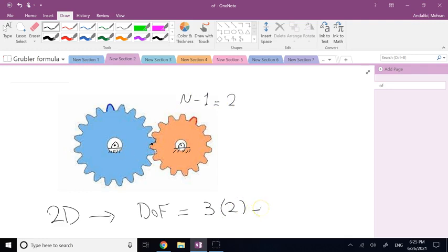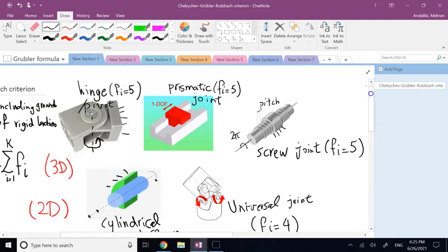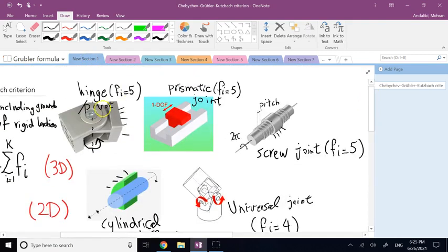Now minus, so here you have 1 pivot and 1 pivot. And what's the degree of freedom that the pivot takes? Well, if we go back, the pivot should take away what? 5 degrees of freedom. But when the problem is what? 3D. When the problem is 2D, 3 out of those 6 motions are not available at all. So all it can take away from you are the 2 translations. These guys are out of the way. You're only down to 1 rotation.